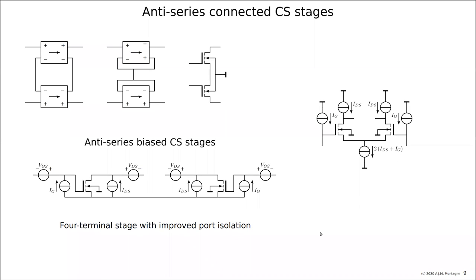And this is the way of design of biasing the whole thing with current sources, because you see all the voltage sources cancel. You don't see them. Of course, we measure them as common mode voltages. That will be on the next page. But as you see now, I have 5 current sources, and the sum of all these currents should be 0.